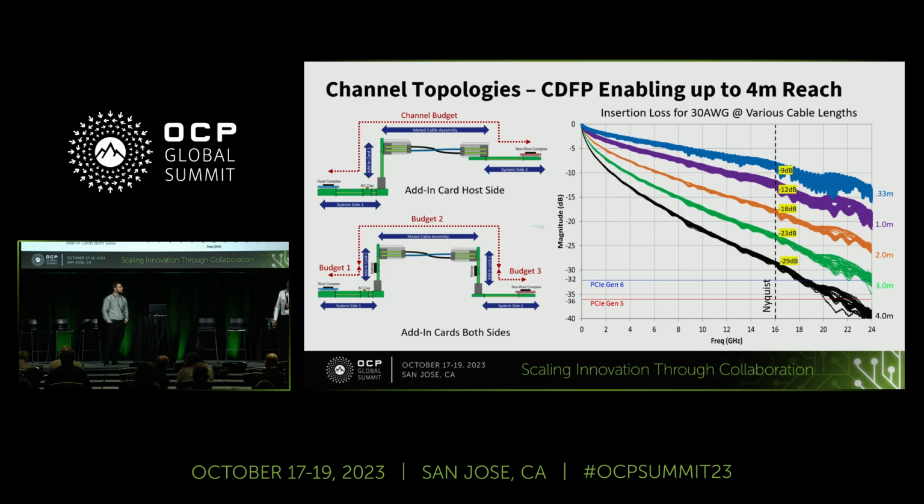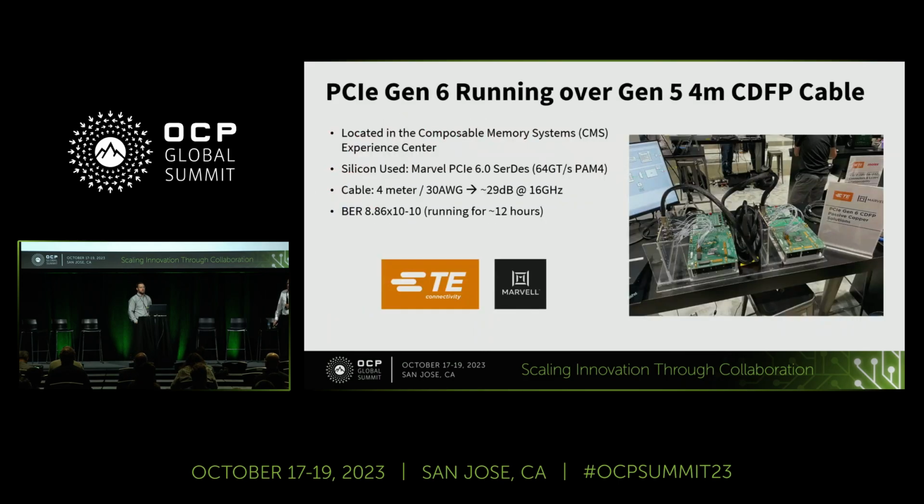Well, the actual retimer, the board, the PCB, and the connector. The receiver of the retimer on both ends is going to have loss there, and that's what we're showing in our demo. That even with all that, this works, with retimers. But if you didn't have the retimers in the channel, you'd have to accommodate for a lot more loss.